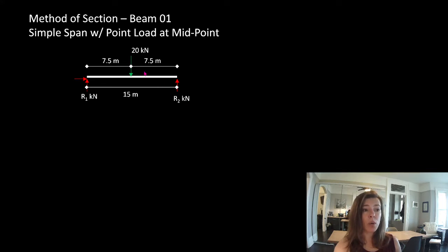We want to know what the internal forces are on this beam, because we know next term we're going to figure out what the capacity of materials are, and we'll need to know if the reduced capacity is greater than the factored loads. But we need to know what the factored loads are this term to be able to do that. So we need to know what internal factored shears and internal factored moments are on this. And we need to then take the worst ones anywhere on this member so that next term we can find the reduced capacities and make sure this beam works.